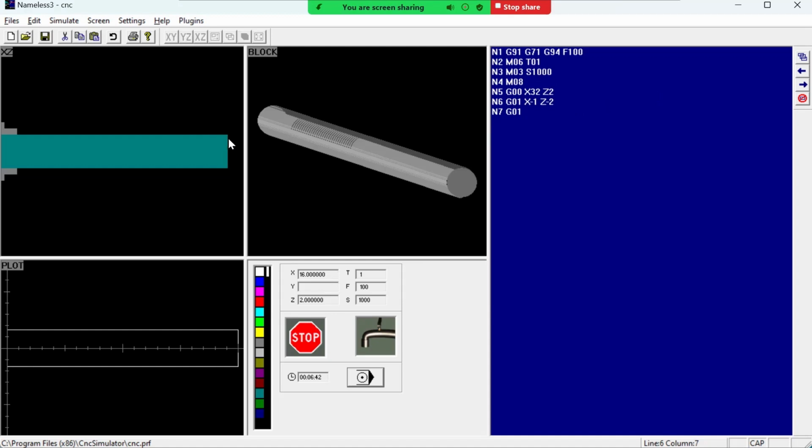So at this point, the tool tip is located somewhere here below the periphery, and it is in contact with the circular end face of the workpiece. Now we want to move the tooltip with the feed rate so that it will do its first pass of the turning operation. Now, as we have mentioned earlier, the origin changes in the incremental coordinate system. So this position, the current position of the tooltip, will be the origin.